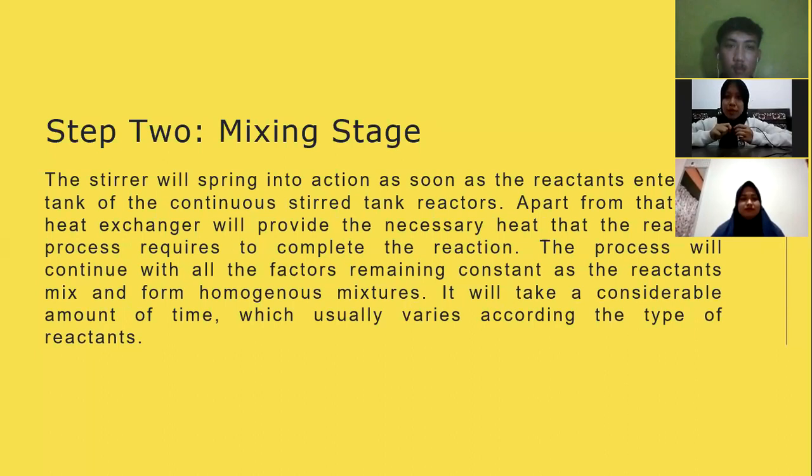Step 2, mixing stage. The stirrer will spring into action as soon as the reactants enter the tank of the continuous stirred tank reactor. Apart from that, the heat exchanger will provide the necessary heat that the reaction process requires to complete the reactions. The process will continue with all the factors remaining constant as the reactants mix and form a homogeneous mixture. It will take a considerable amount of time, which usually varies according to the type of reactants.